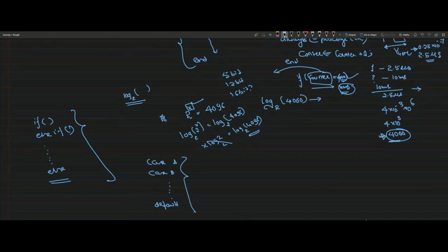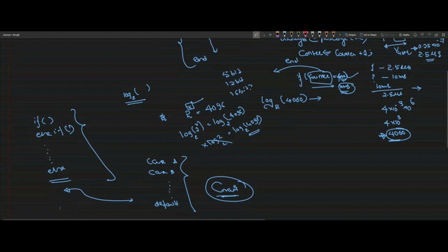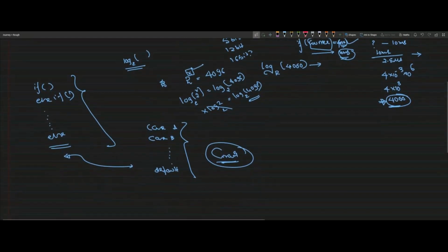If someone asks you to design the circuit for these different scenarios, can you tell me what kind of circuitry will be inferred in the FPGA for the if else statement and the case statement? If else is a D flip-flop. Not really. You can assume in the case of combinational logic you can also have if else. D flip flop will come into the picture when you want to infer one.